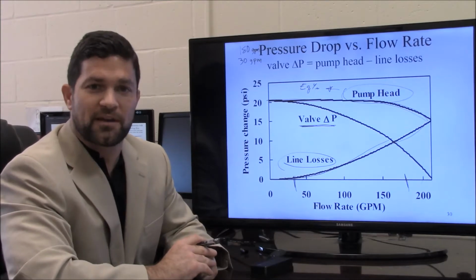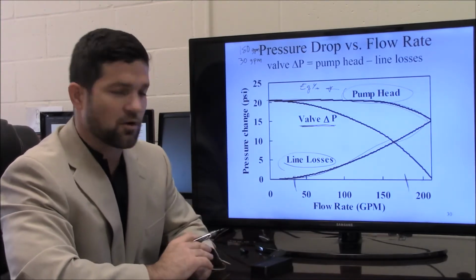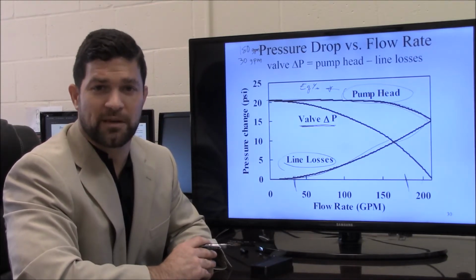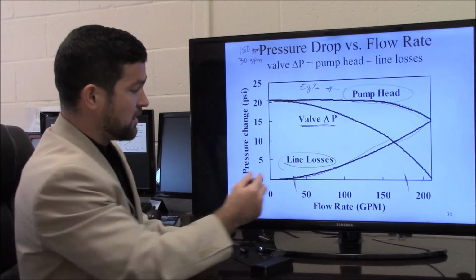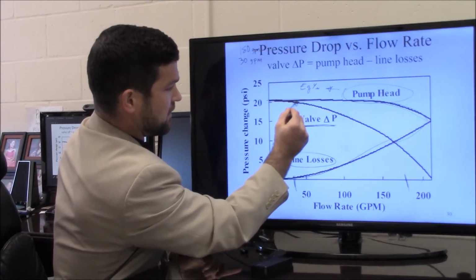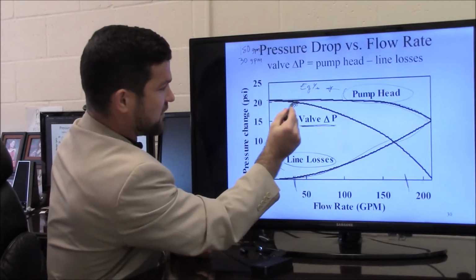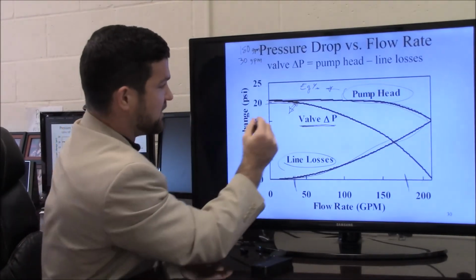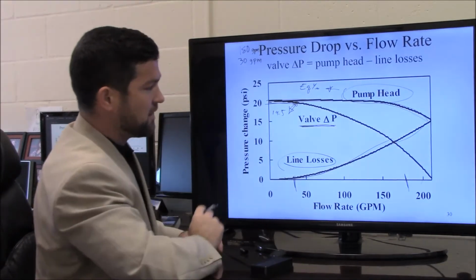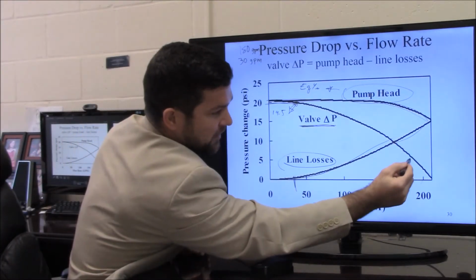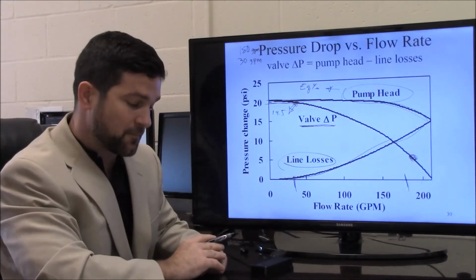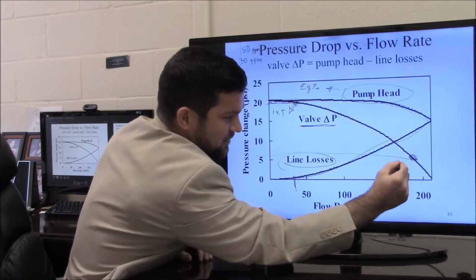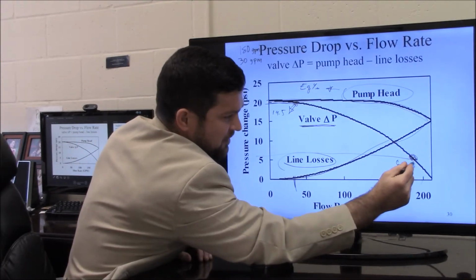Okay, so for the equal percentage valve, we'll use table 2.1, and I can go back to that valve table in just a second. First we want to know what our delta P across the valve is at the minimum and maximum flow rate. At the minimum flow rate, if I read this off the plot, maybe that's between about 19 and 20, so I'll say 19.5. At our maximum flow rate, we're somewhere around here. If I draw this over here, maybe this is about 6.5 psi.